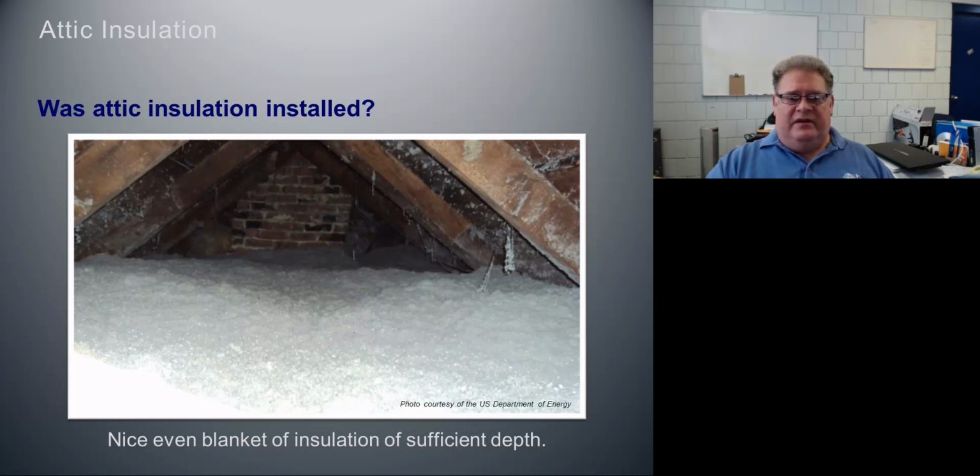How about here? We've got a beautiful blanket of insulation, okay, to depth. So we have insulation that's installed, and it appears to be installed properly. However, look all the way at the back of the picture. What do you see back here? It looks like we have a masonry chimney back here, and we've got insulation that appears to be right up against it.